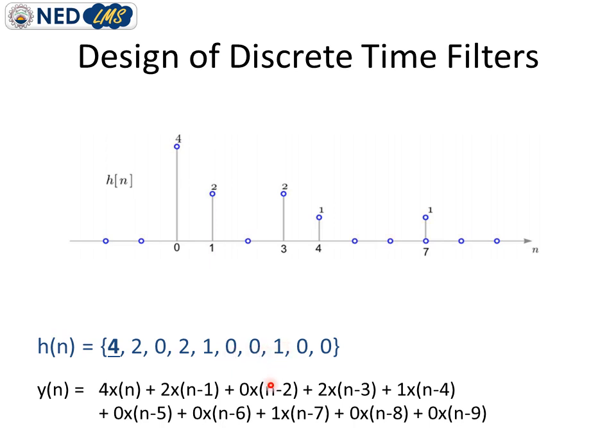But by doing so, I can minimize the cost of system design as I am utilizing fewer delay blocks and other blocks, which are addition blocks or multiplication blocks. So my system is not very complicated by omitting the last three coefficients, but again I have to compromise on the response obtained from that system.